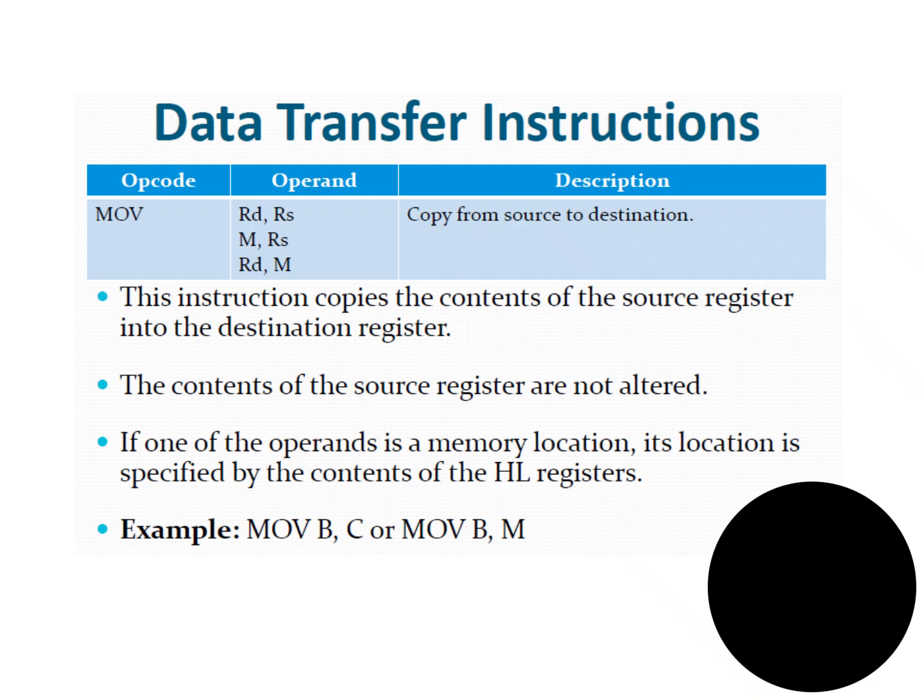One of the instructions, or mnemonics, which we use is the MOV instruction: MOV RD, RS, where RS represents the source and RD represents the destination. We have many general purpose registers, which are B, C, D, E, H, L and A. Individually, these registers can be used as 8-bit registers.